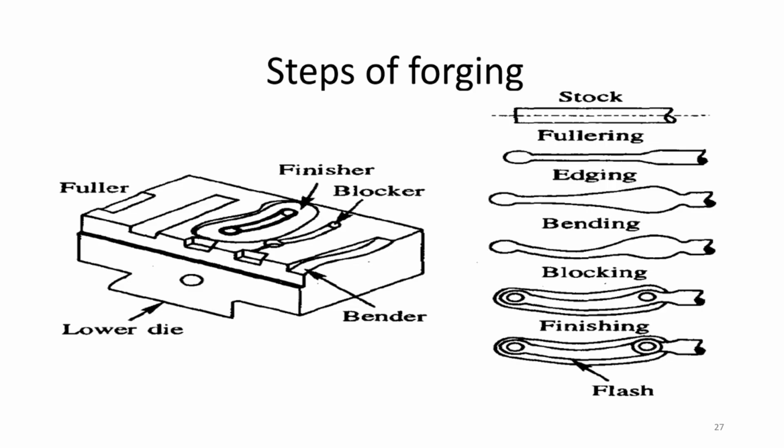Ma'am, when we are studying the TTT diagram, whether this austenite locking will be happening. I mean, if we austenize the steel and quench it, we will be getting martensite without touching that nose, isn't it? So does this locking of austenite happen when we are cooling at a rate faster than the martensite formation rate, or is that correct?